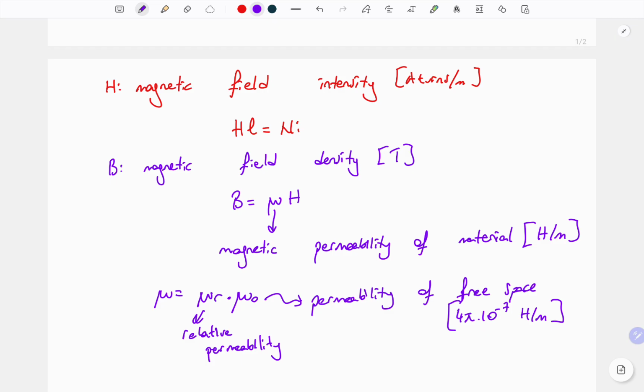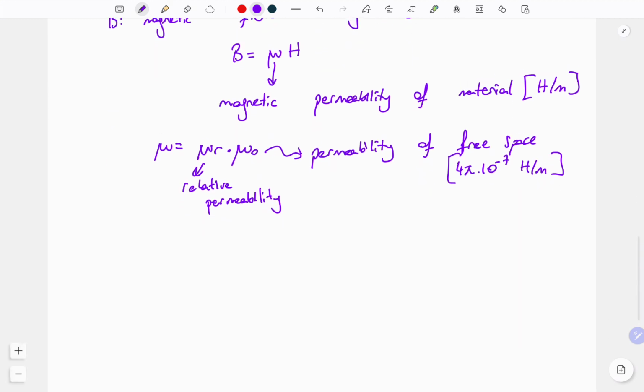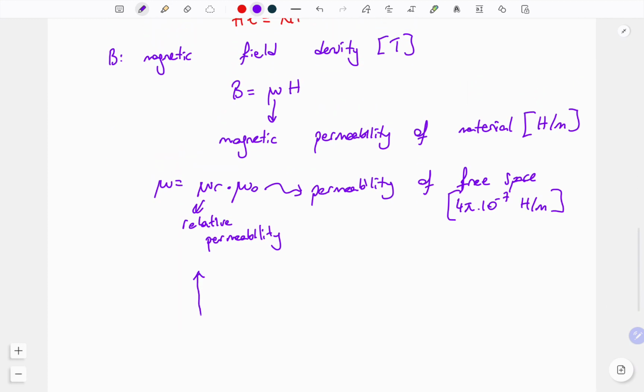And in terms of your losses, which affect the magnetic losses inside the magnetic core, we need to consider this relative permeability value further. But before this, let's try to understand the relation between B and H in detail. For this, we need to analyze the relation between B and H by using the magnetization curve. The magnetization curve shows this relation, and we have a nonlinear behavior between B and H. And we have two regions.